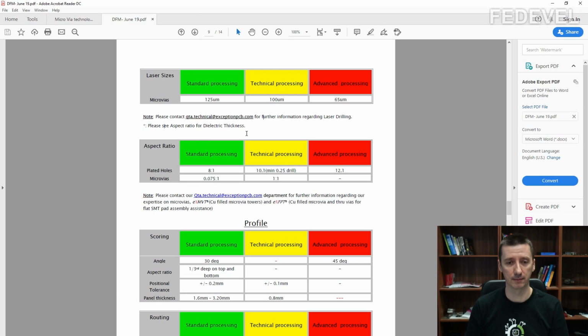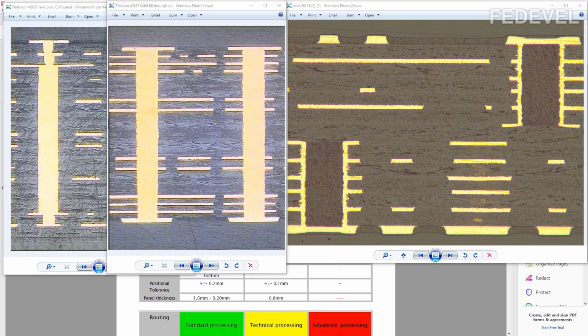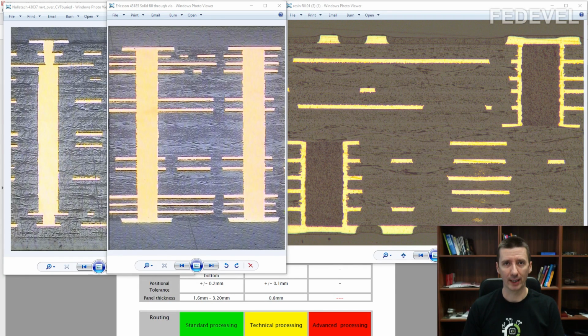Very, very important. We have learned a lot about standard vias and standard microvias, but we would like to learn about via in pad. What is the difference? The difference is that you take the standard via or standard microvia and you place it into a pad. But you cannot use it like this. What you need to do, you somehow need to place copper on the top of the via, so you can nicely solder the components on the top of the pad. If you don't put the copper there, then there would be a hole. And there are more options for how you can do it.